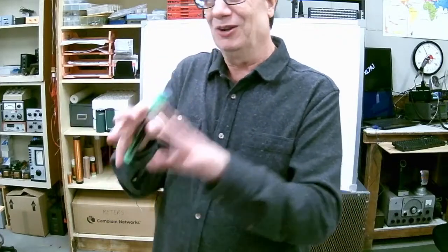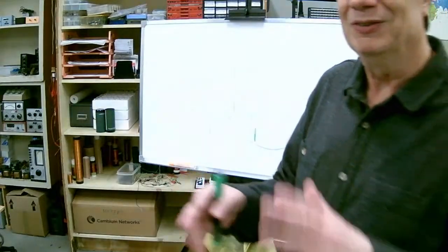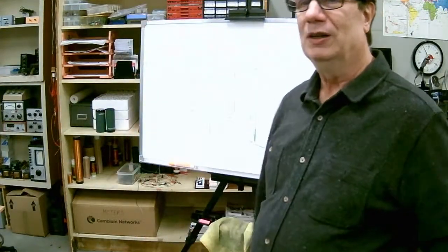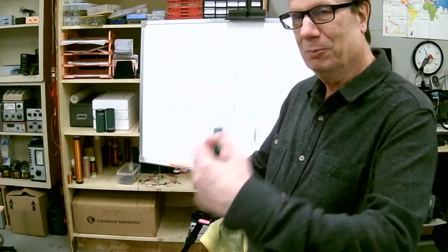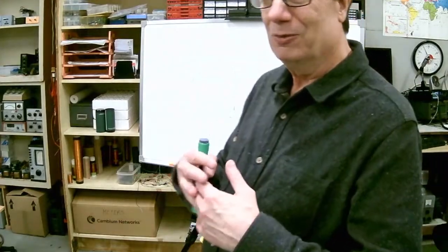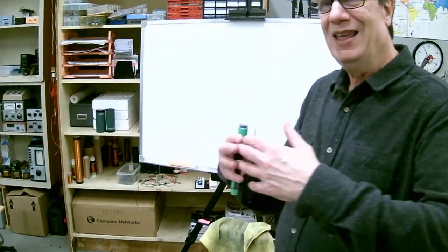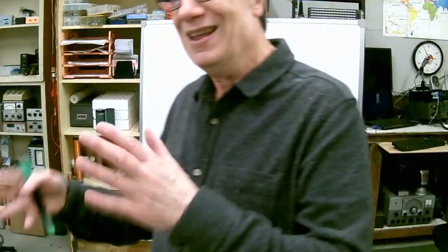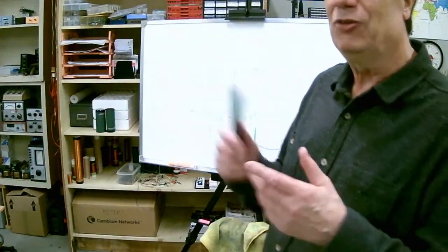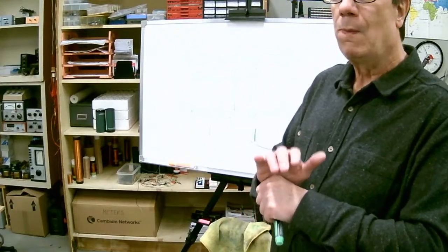So they're actually interlacing themselves there, so they aren't on the same frequency at the same time. They synchronize there. There's a frequency division multiplier where you simply do it by slots. There's also what's called spread spectrum, where they randomize where the frequency is within range, and it's only if you have the decoding to de-randomize it that you get the signal. So they actually do overlap frequencies on cell phones.